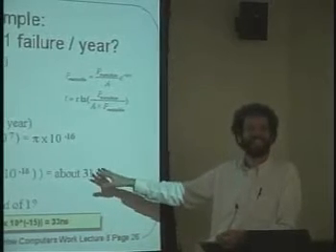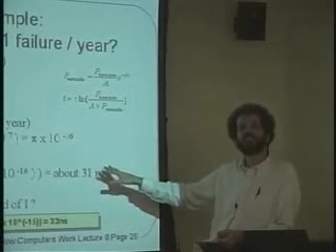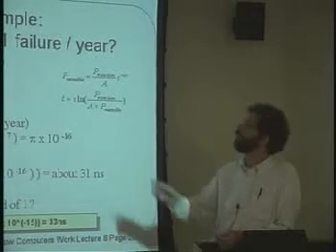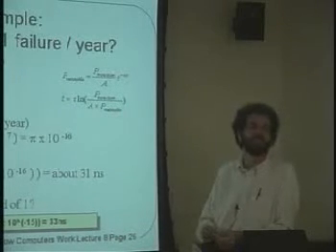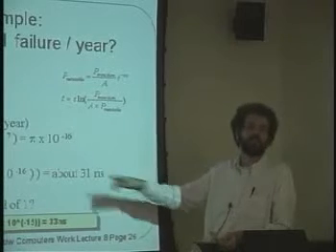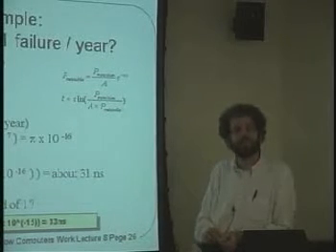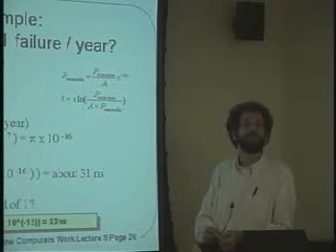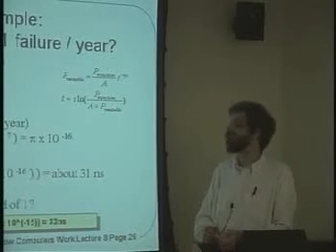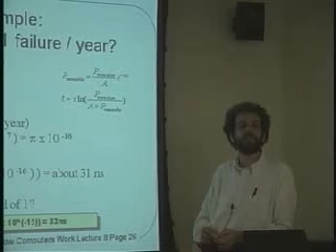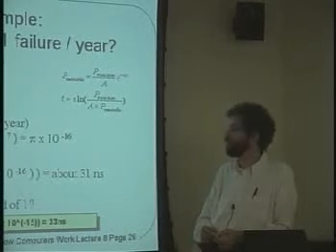But it is a tremendously long length of time for a processor that's going at 100 megahertz, or these days one going at a gigahertz. This is 31 clock cycles for a gigahertz processor that need to be wasted while idling away, waiting for the flip-flop to come up with the answer. And while we're waiting for it to settle down with the answer, we could be doing other work. So we're going to have to figure out some way to fix this.